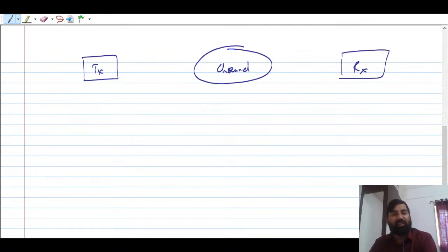What kind of preparation do you need? There are various requirements. First of all, you need to keep your signal at low bandwidth. The signal should not have huge bandwidth. Otherwise, you cannot send many signals to the channel. That is one thing. And now we want to keep our message signal at very low bandwidth, minimum frequency, minimum bandwidth. Then what problem are you going to face?